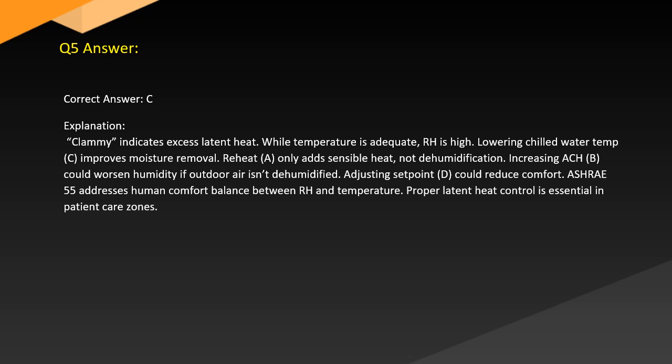Increasing ACH, B, could worsen humidity if outdoor air isn't dehumidified. Adjusting set point, D, could reduce comfort. ASHRAE 55 addresses human comfort balance between RH and temperature. Proper latent heat control is essential in patient care zones.